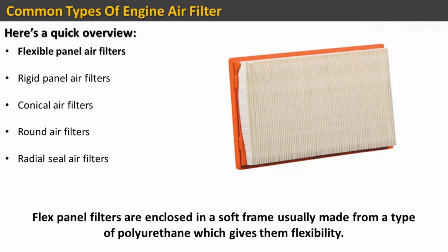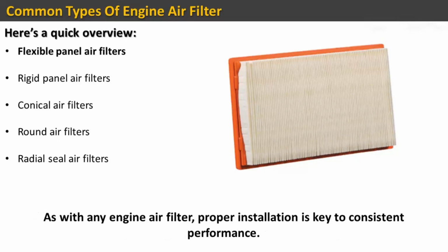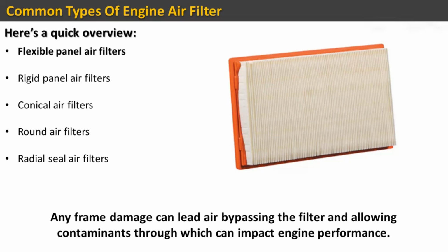Flex panel filters are enclosed in a soft frame usually made from a type of polyurethane which gives them flexibility. While this makes them easier to install and remove, it does mean the frame can be damaged through rough handling. As with any engine air filter, proper installation is key to consistent performance. Any frame damage can lead to air bypassing the filter and allowing contaminants through, which can impact engine performance.